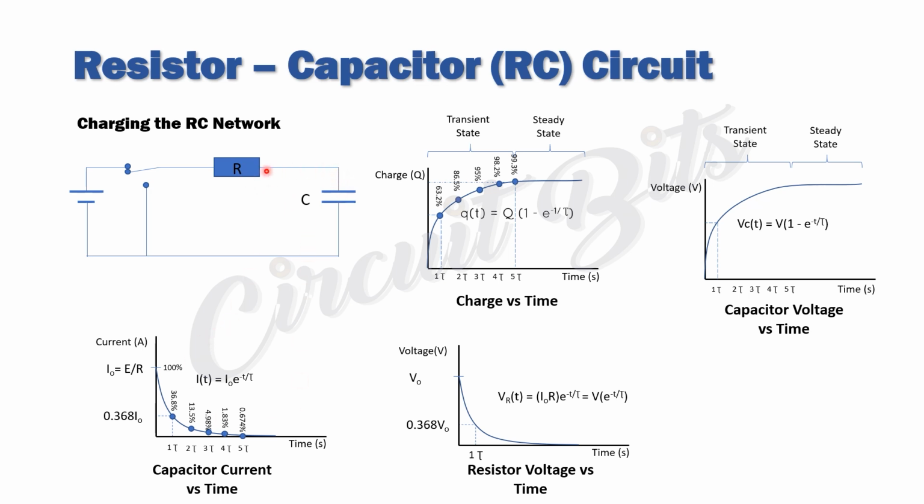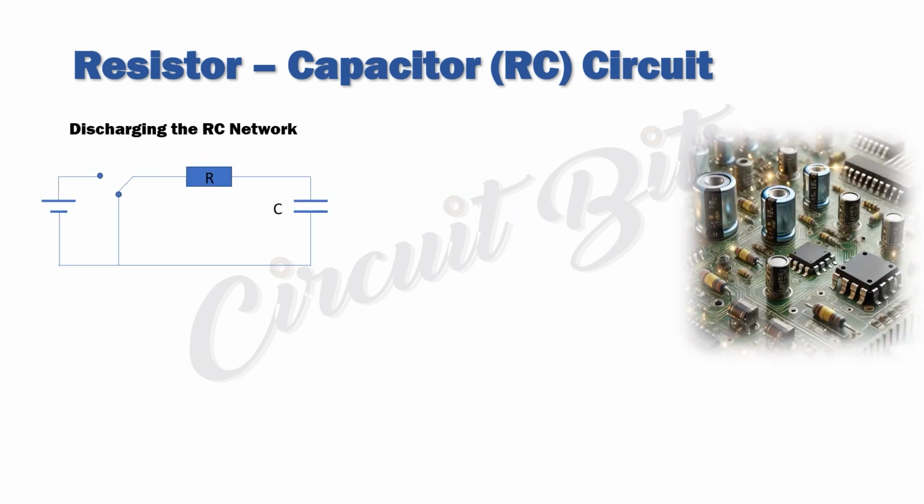So we're going to have this wire here at zero potential at the beginning, just when this starts taking in current, because it's going to act like a short. So if we consider the voltage on this side with respect to the voltage on this side, we'll have this resistor at maximum voltage just when you switch this on. And as the capacitor continues to charge, this place will begin to build up voltage and then reduce the voltage reading across the resistor.